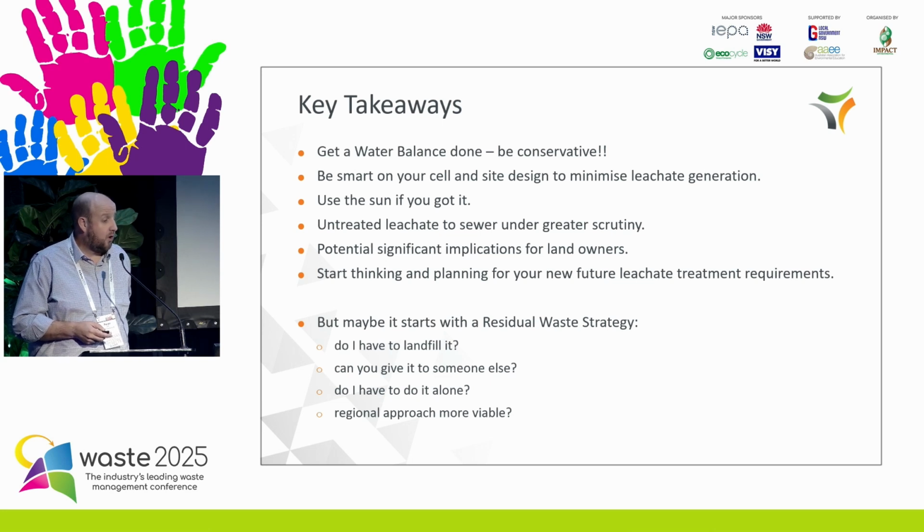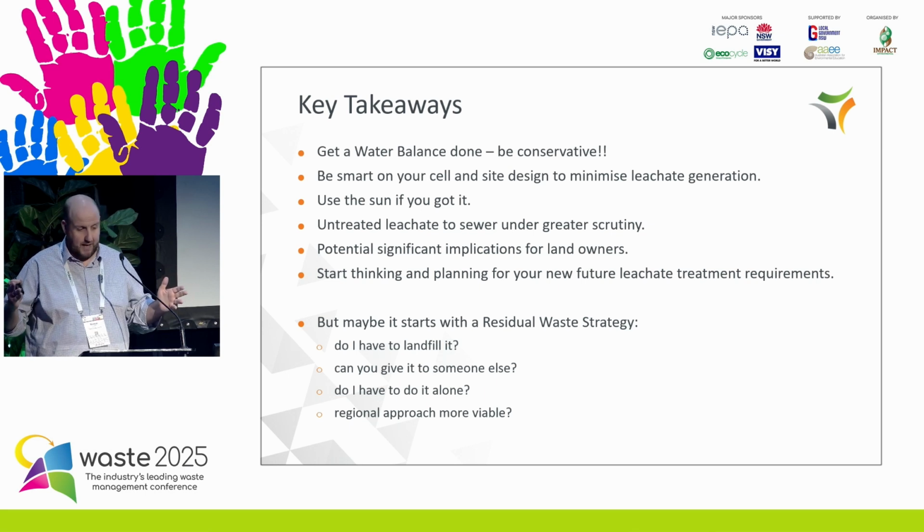Key takeaways, guys. Just to summarise what I touched on: get a water balance done. Obviously, it's absolutely critical. You can only manage what you can measure, and be conservative in that approach. Be smart on your site design, particularly when you're setting up. We've been lucky enough to be involved in projects that are starting from day one, site selection studies, design, approvals, all the way through, and it's great. You can really see how being smart in your design is minimising your risks and your operational issues and challenges later on. And of course, leachate is the main thing we're trying to avoid in relation to landfill engineering. So being really smart on that.